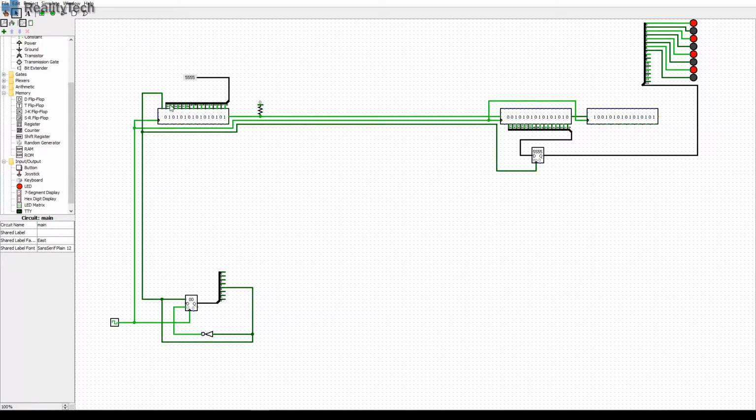You can send an address in here and then use the outputs of here to drive a multiplexer. That gives you a fourth line that allows you to select. If you use analog multiplexers, you'd be able to select an analog signal out of, in this case, quite a lot of inputs. 16 bits gives you more than ample analog inputs for most things.